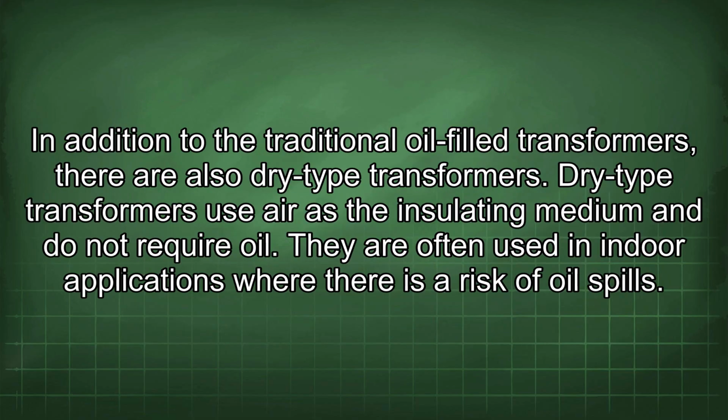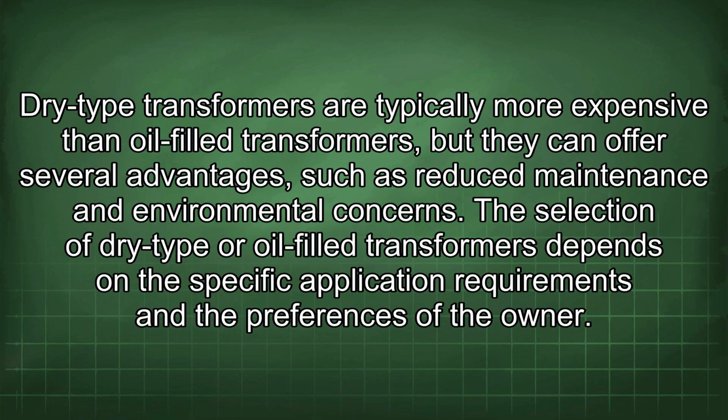In addition to the traditional oil-filled transformers, there are also dry-type transformers. Dry-type transformers use air as the insulating medium and do not require oil. They are often used in indoor applications where there is a risk of oil spills. Dry-type transformers are typically more expensive than oil-filled transformers, but they can offer several advantages such as reduced maintenance and environmental concerns. The selection of dry-type or oil-filled transformers depends on the specific application requirements and the preferences of the owner.